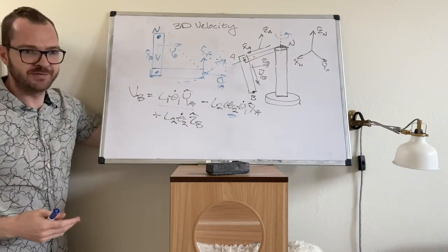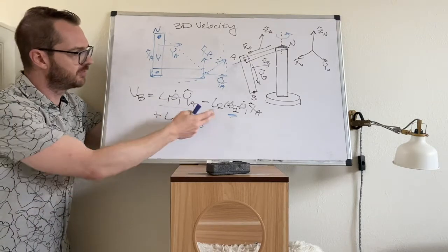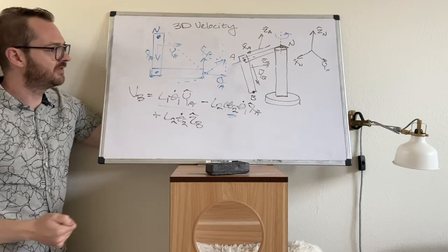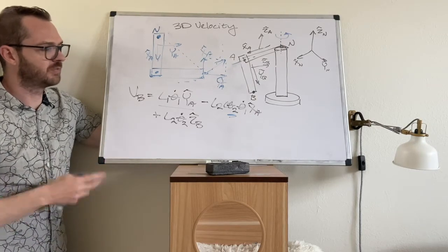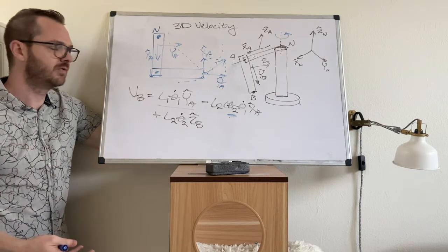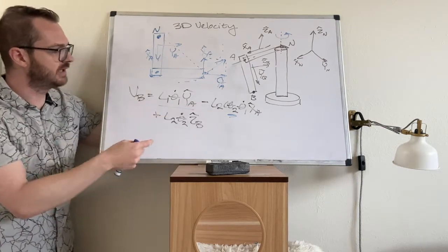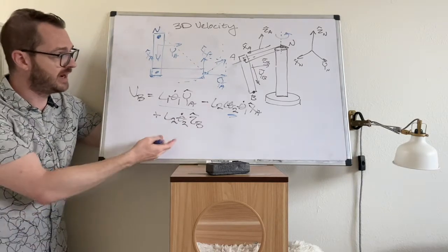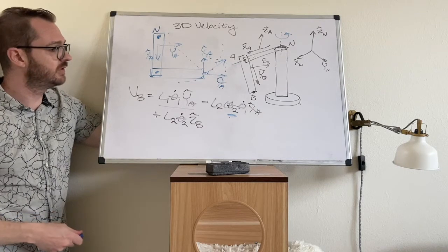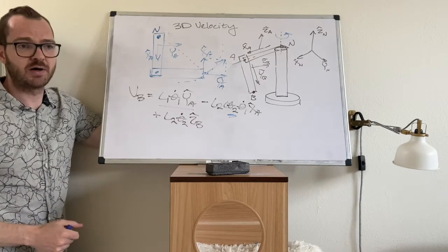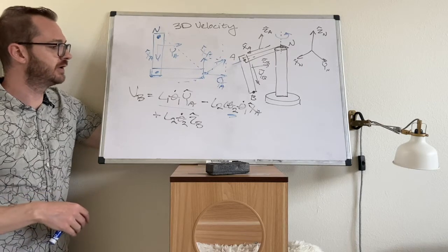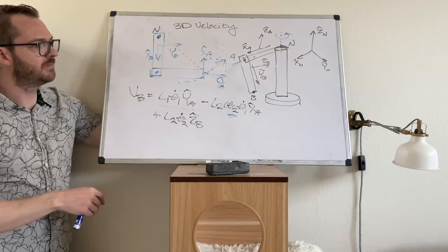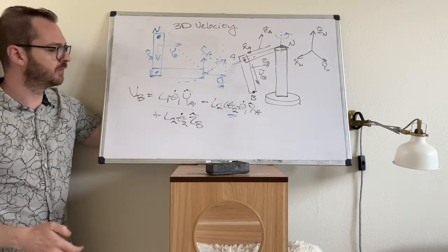When the problem gets very complex, these terms are going to get nasty. They just are. So again, this is why when we do very large problems, especially problems with a lot of bodies, we use software tools. Whatever these expressions come out to be, it can be cosine of this and sine of that, because you have done so many rotations. That is simply the math. And once the system gets really big, beyond 8 to 10 degrees of freedom, we don't actually have these things solved for explicitly. There's no symbolic math anymore. It's all just done numerically inside of a computer.